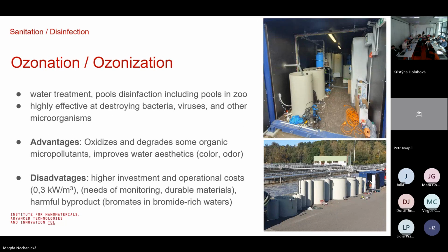Ozonization is a very nice method. In the past it was claimed that it's quite expensive. This is not really true. Here, these pictures are from our pilot site at the wastewater treatment plant in Liberec. We use this method for final sanitation of water in combination with oxidation of remaining micropollutants.